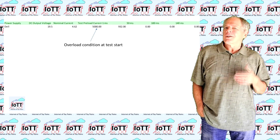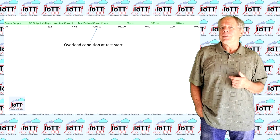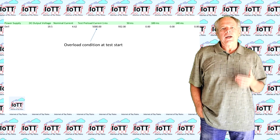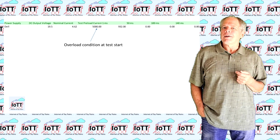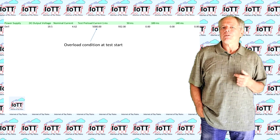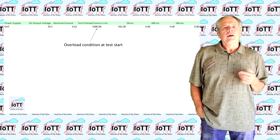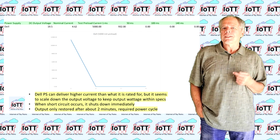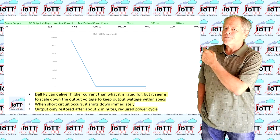When I saw that, I could not resist repeating the test with a starting current that was higher than the nominal output current. So I hooked up the Dell power supply and preloaded it with 5 amps, which is about 10% more than the nominal current of 4.62 amps. When I ran the short circuit test, it shut down before the second reading, at around 50 milliseconds, as seen here.